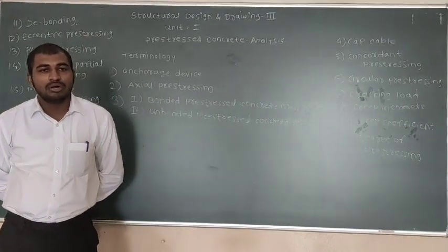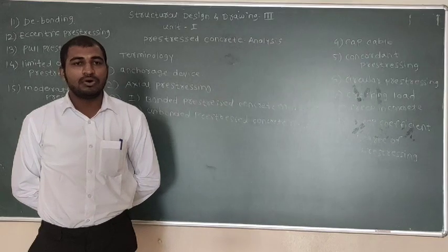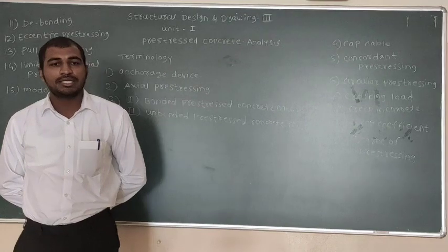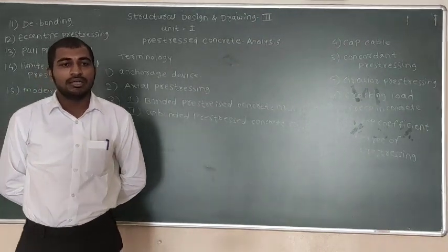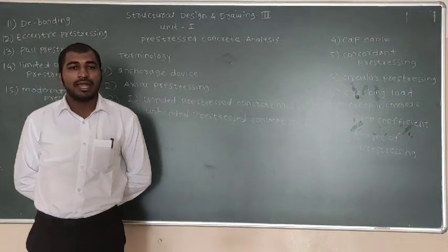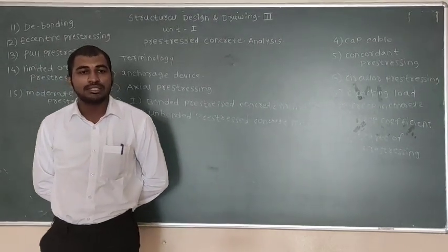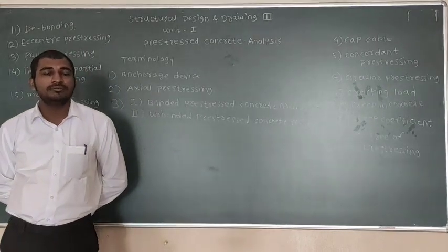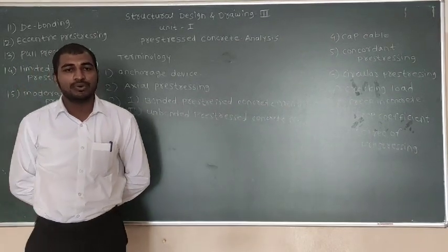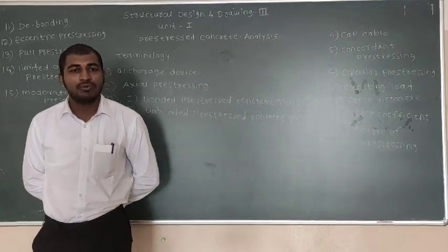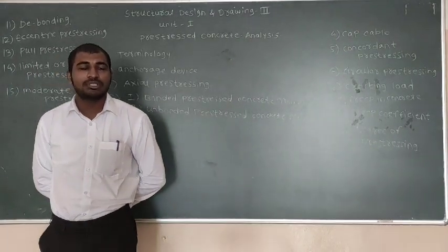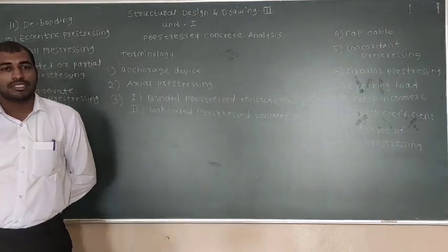According to Leonhardt, this form of construction is not really prestressed concrete but is to be regarded as reinforced concrete with reduced cracking, and cracked sections should be analyzed according to the rules of reinforced concrete as a case of bending combined with axial force. This is moderate prestressing.